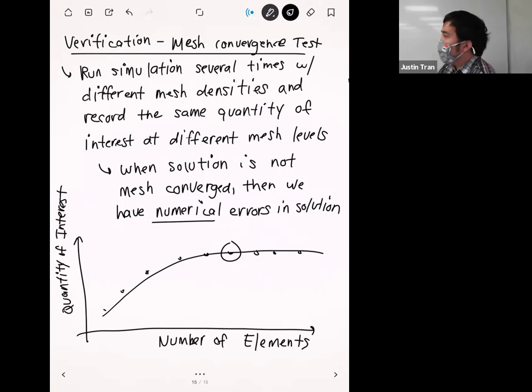And I think when you're first coming to finite elements, it seems like a lot. The limit for the academic version is maybe close to 100,000. Like I saw some reports that you had element counts in the 90,000s. That might seem like a lot, but in reality, it's kind of not. For a lot of practical finite elements that I've seen people do, they have element counts in the 500, 600,000s. And for my own research, I usually don't feel comfortable unless the element counts are in the millions. 2 million, 3 million, 4 million is pretty standard.